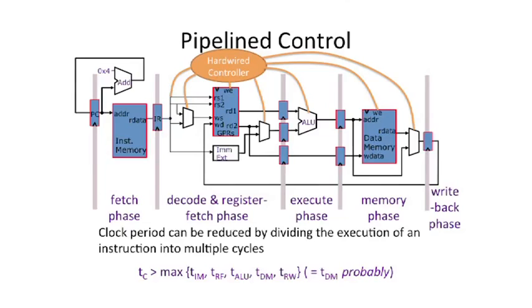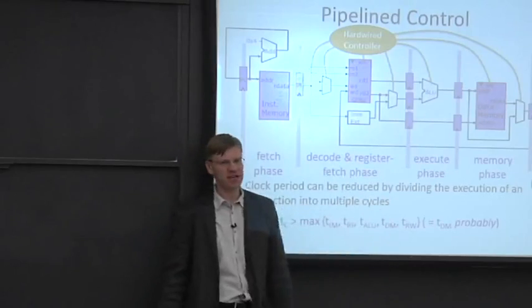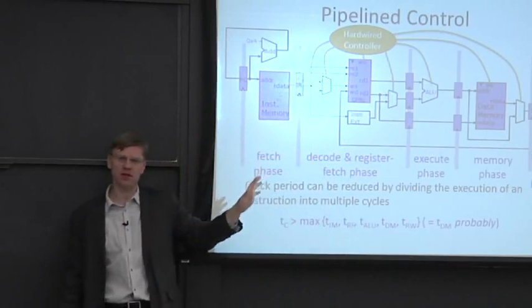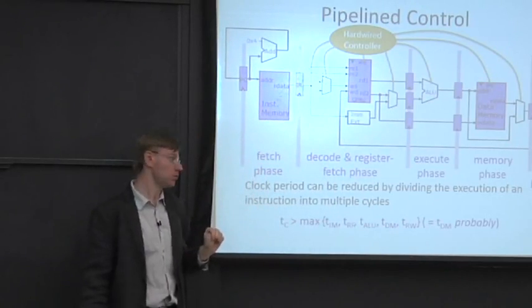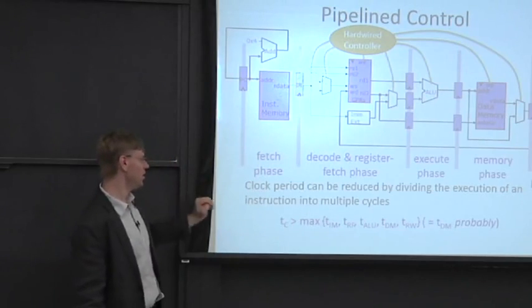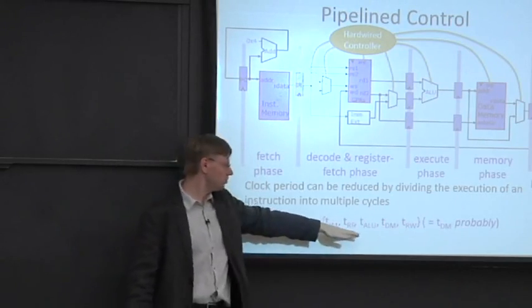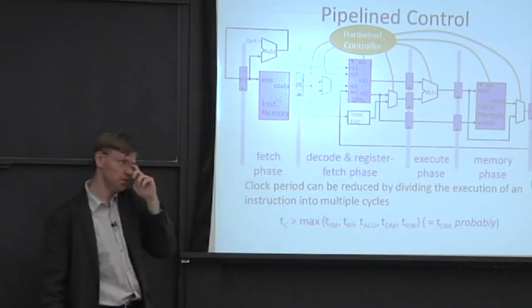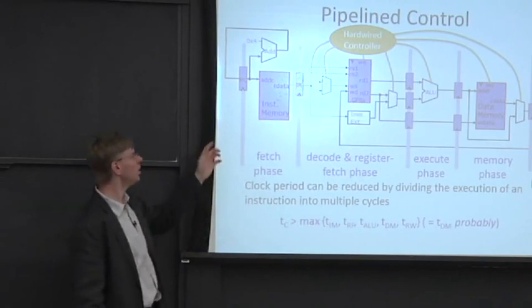Actually, before we do that, let's first look at how to use this processor in a multi-cycle yet pipelined fashion. So what do I mean by that? Well, let's say we're going to use the same data path and use the exact same control unit we had in the unpipelined MIPS processor. And in this design, the cycle time is now, let's say, close to 1/5 of the cycle time we had before, because we had 5 pipeline stages. So our processor executes faster.